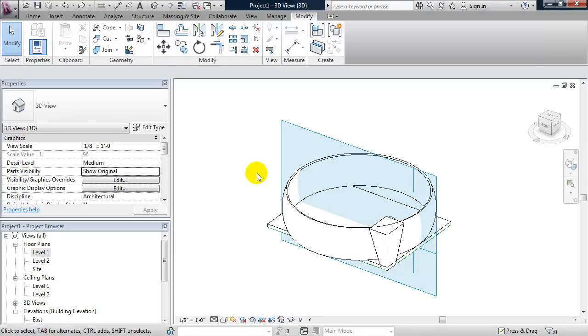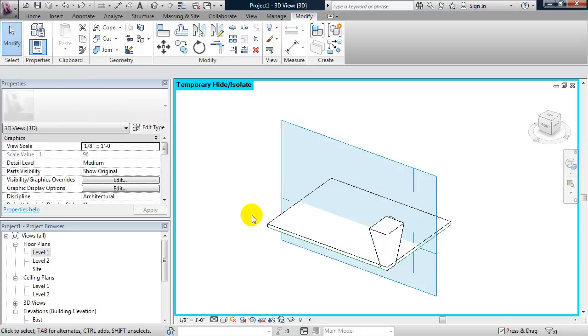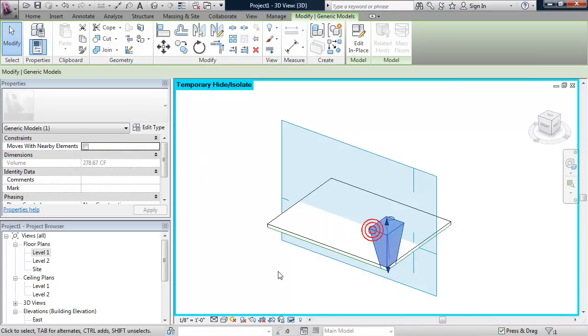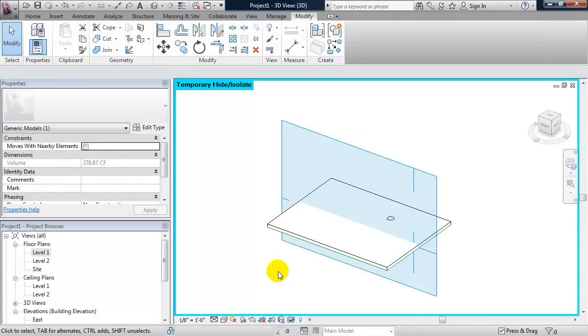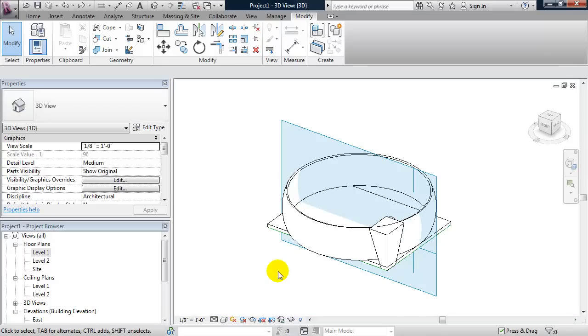Now, I'm going to sweep along the top of this slab. So I can turn off some of these objects. And what I'll do is I'll hide them temporarily so it's easier to get them back. So if I select an object and I type in HH, it hides it temporarily. I can select that column and type in HH. Now if I Control Z a couple times and bring those objects back,